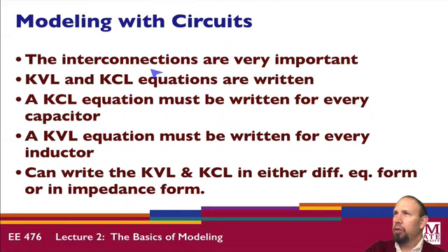So in general, the interconnections are obviously very important. KVL and KCL equations must be written. A KCL equation must be written for every capacitor. A KVL equation must be written for every inductor. You can write the KVL and KCL equations either in differential equation form or impedance form. So using impedance is another way of working with circuit components.